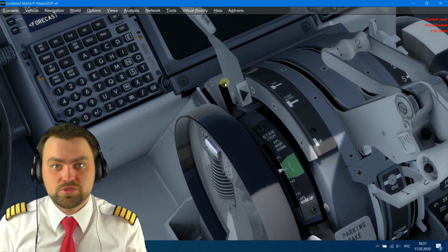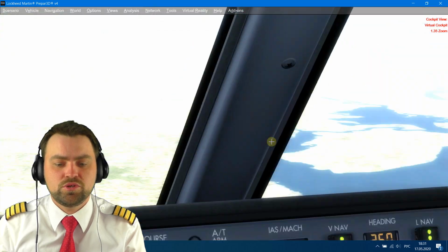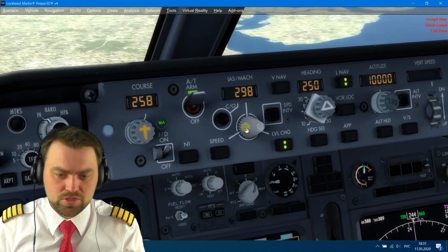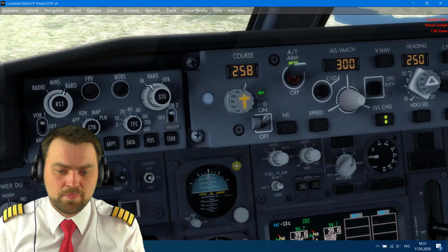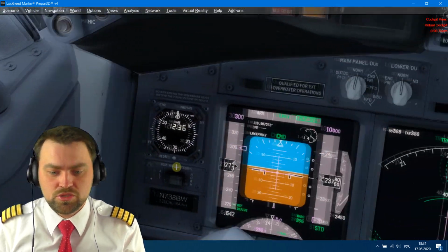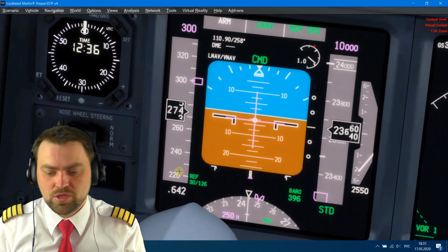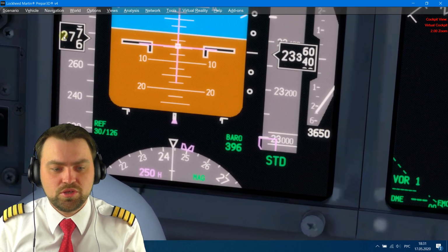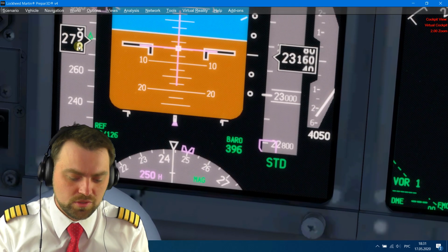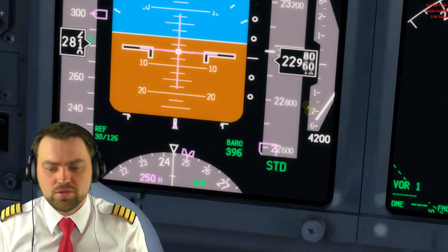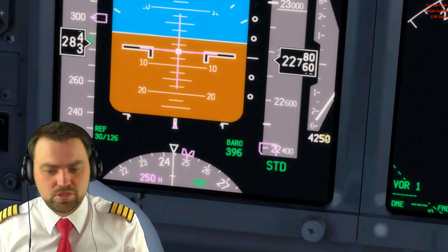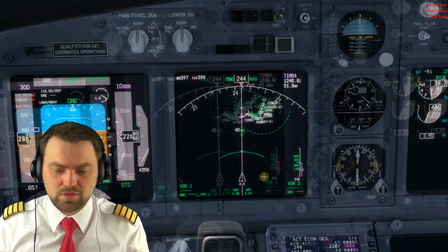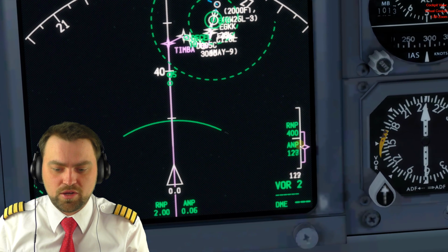Also, if you don't have speed restrictions from the air traffic controller, you may also use level change. With level change, you can increase your airspeed, let's say to 300 knots, and you increase your kinetic energy, and at the same time, let's see what happens to the vertical speed. The more airspeed you have, I'll just put the full screen, the more vertical speed you have. You see, it's a lot, even with the speed brake retracted. And you're reaching your profile.